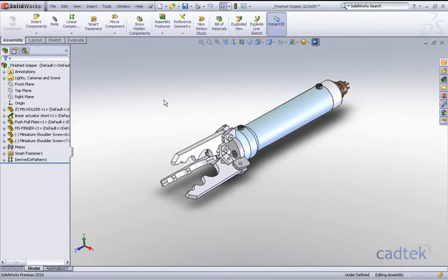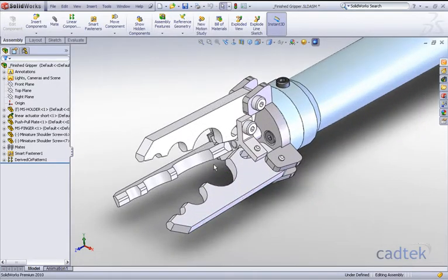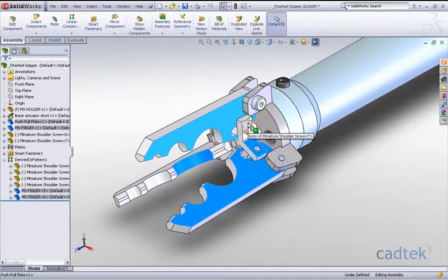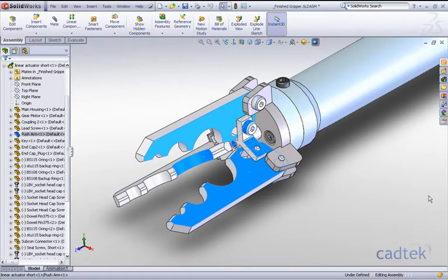Another way to be a little bit more selective is by using the tag command. Now if I just zoom in and select a number of components, you can see we're just running through and selecting half a dozen or so components. I'm going to go down to the bottom right hand corner, where I've got a little tag button. If I click on here and click in the box and type in any characters, so we're just going to type in the word moving, I've added a tag to these 6 components.